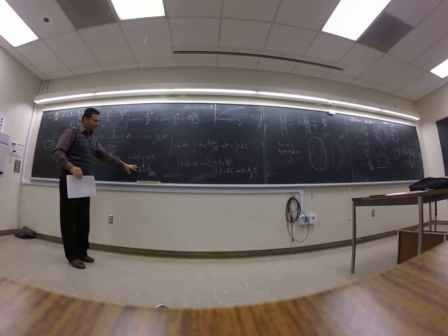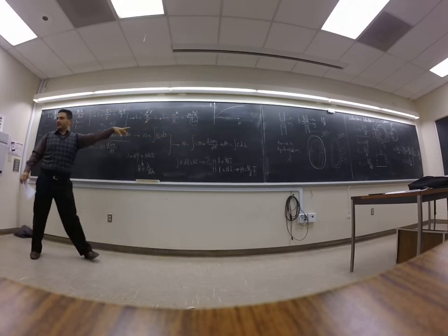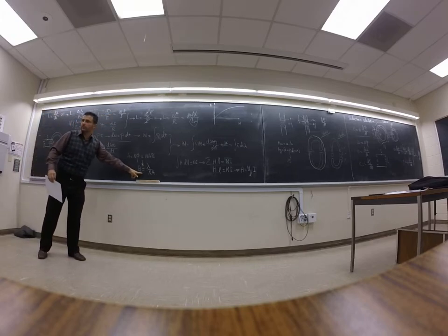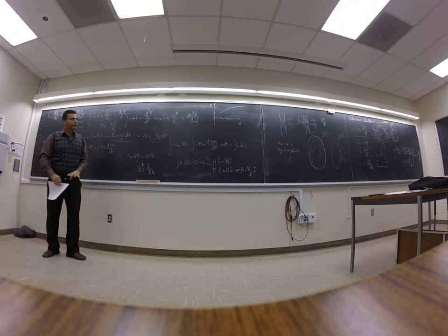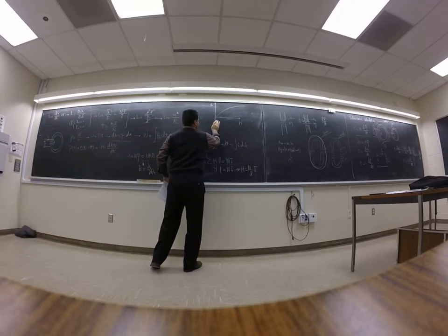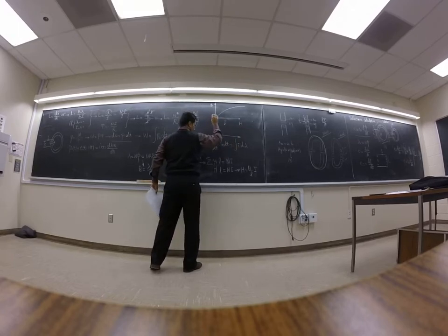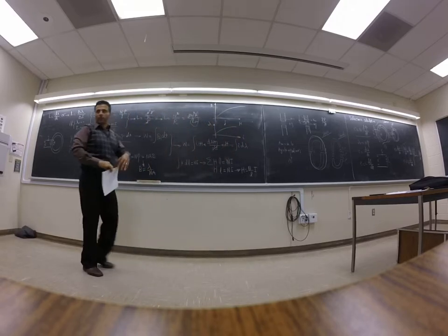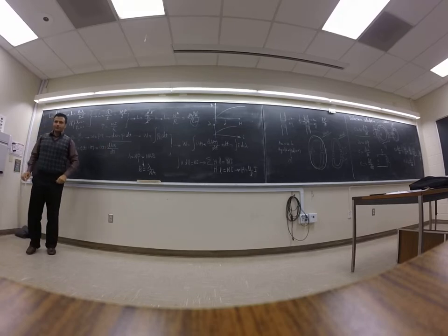So look at here, if I want to change this curve from BH to lambda I, I can use this equation and that equation and convert all these things to lambda and I. So this one can go to this curve. I think it was lambda here, I here, and something like this. So my point is when you have the BH curve, we can get to the lambda I curve, right? With these two equations I put here.